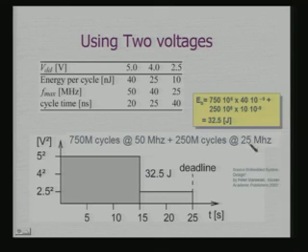25 megahertz means I can now have a supply voltage which is what? Less, okay. And correspondingly, I see that at this supply voltage, my energy per cycle is also much less, not 40. So, if I add these two up, I get 32.5 joule, which is definitely less than 40 joule. So, what am I doing? I am dynamically switching the voltage as well as the frequency.